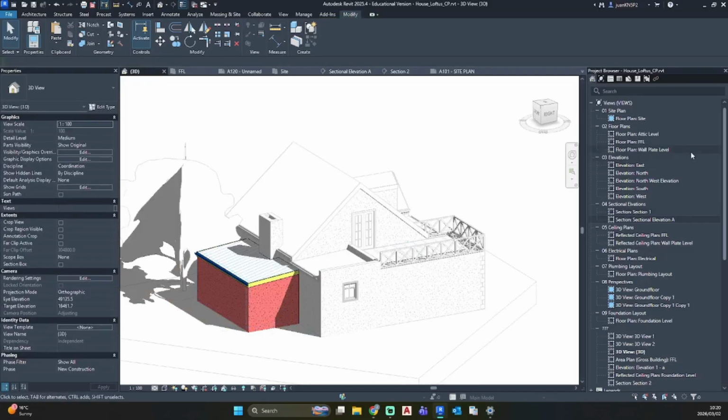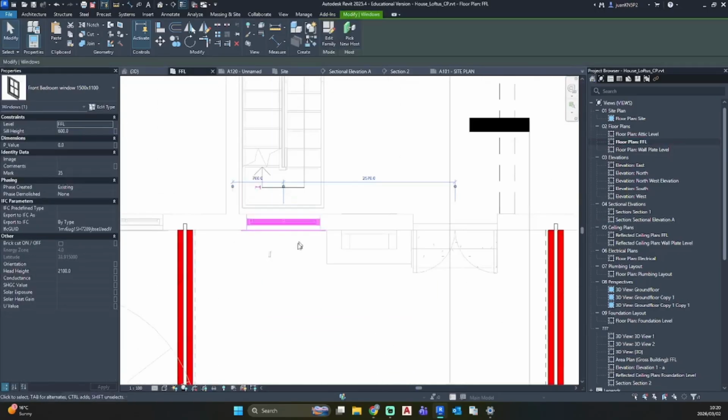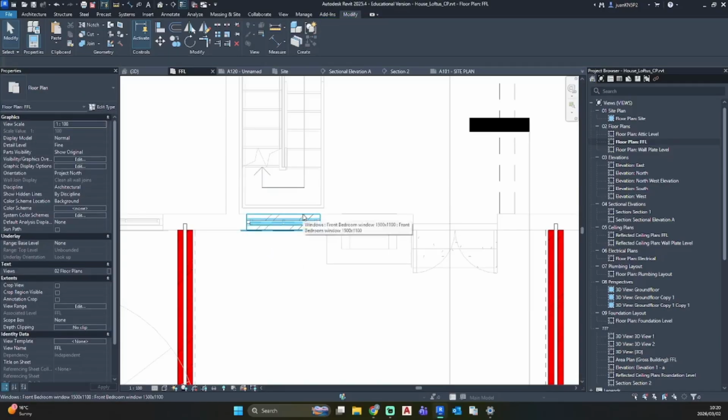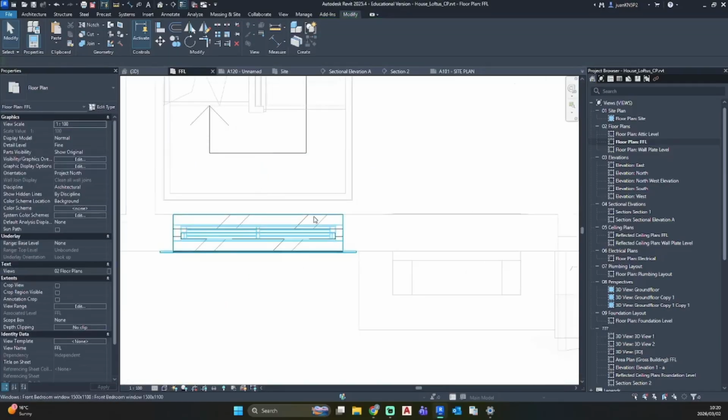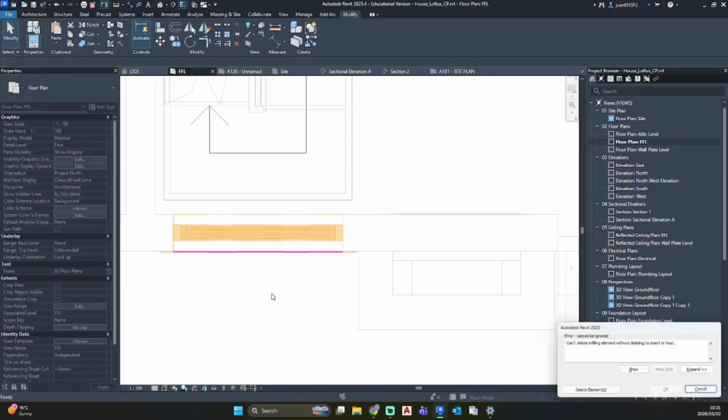Now we just need to go into floor plan, and I'm going to select this window because we are going to take out this window and keep it an opening with a nice little railing. So I'm going to go, it's created in the new phase, but we want it demolished in the new construction phase, like so. So now I'm going to hover here and go tab and select this brick wall because we are not breaking it up.